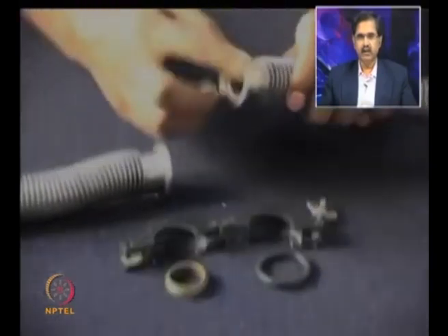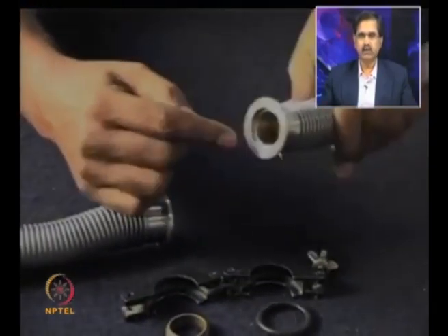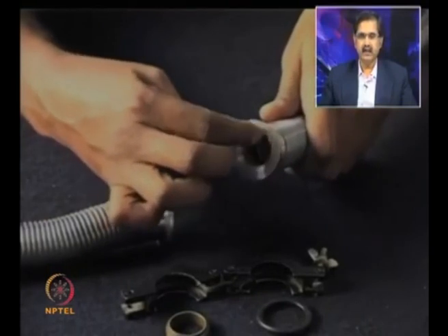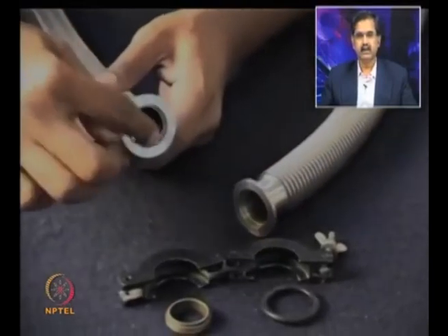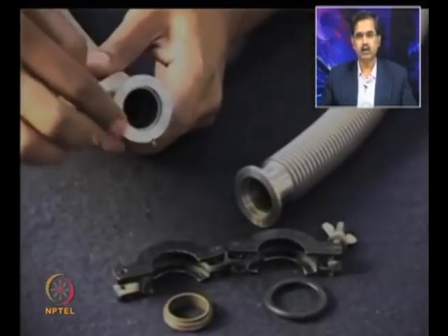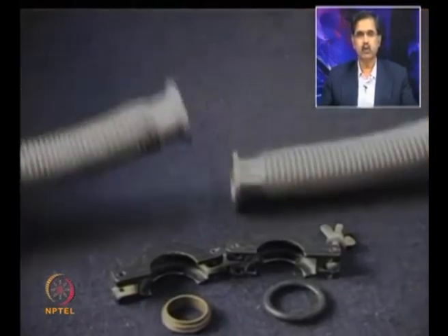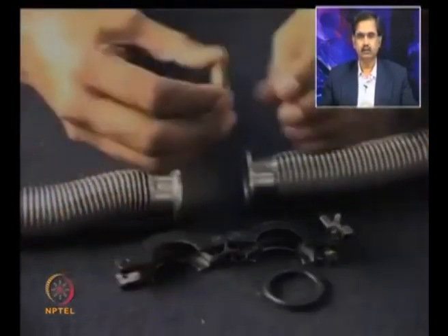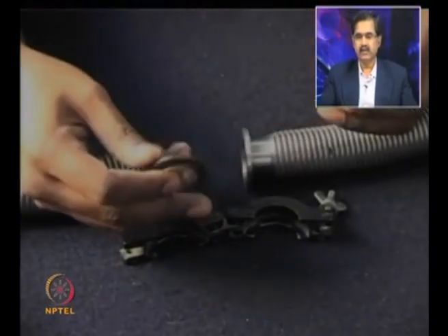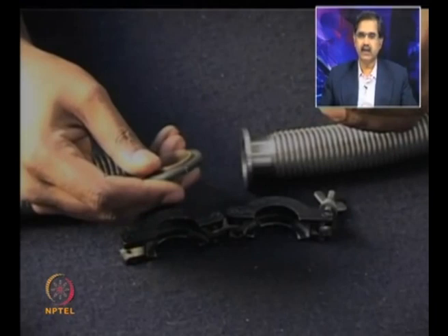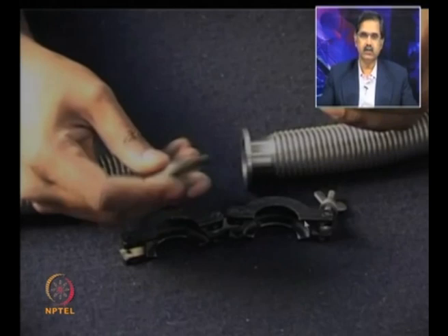So, we just saw the coupling's three parts, and now you can see a vacuum hose which has a diameter, and this can be a KF 25, that means a 1 inch kind of size. Similarly, you have a 2 inch coupling also. Whatever you want to use, and you have two hoses now, and using this coupling we want to connect these two vacuum hoses. You can see how the rubber is held on this brass housing. This will have the same ID as this, and this will now be connected with this using this coupling together. So, let us go ahead.